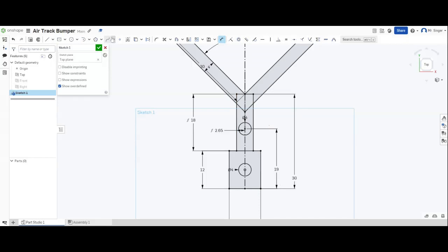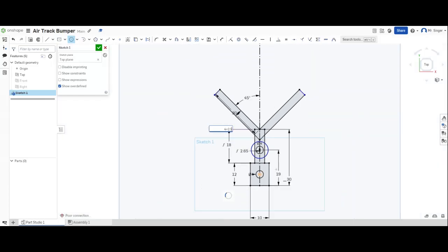And now we're going to make a concentric circle to give some width on the edges. And this is going to be 2.5 millimeters bigger than the inside circle. So we're going to go, once it loads a little bit, 4 plus 2.5. And when the computer finally decides to load, we will be done with sketch 1.